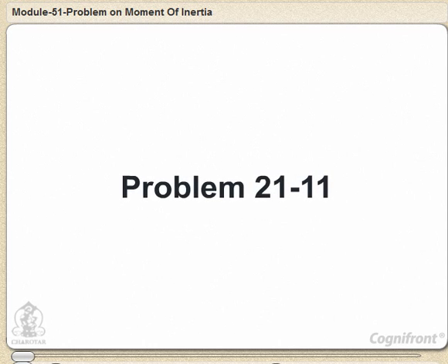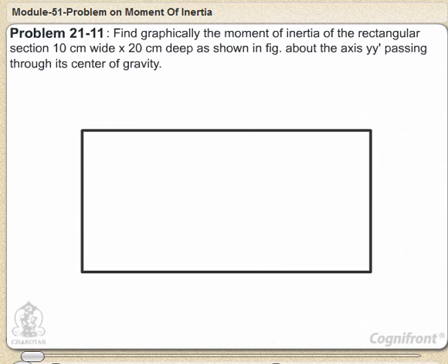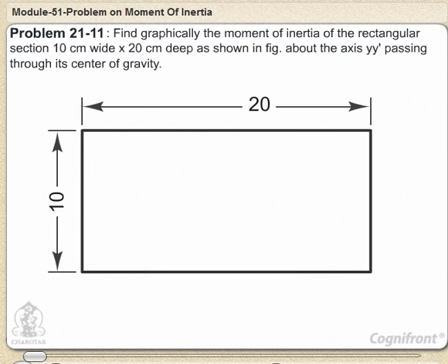Illustrative problems on moments of inertia. Problem 21.11. Find graphically the moment of inertia of the rectangular section 10 cm wide into 20 cm deep as shown in the figure about the axis y dash passing through its center of gravity.